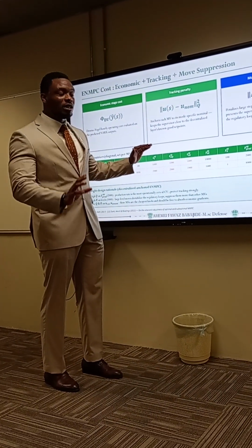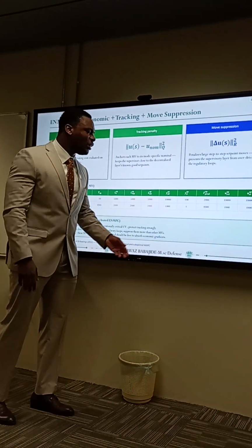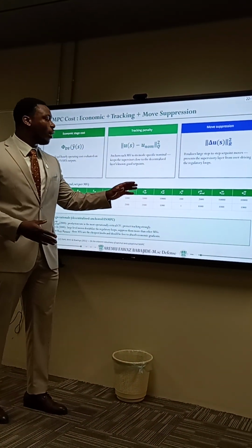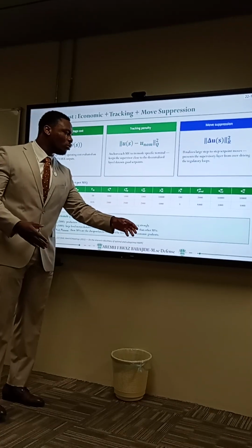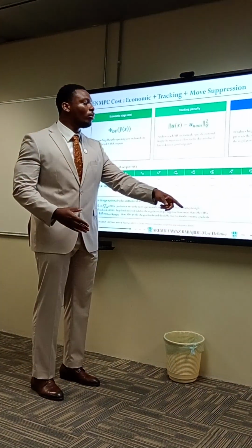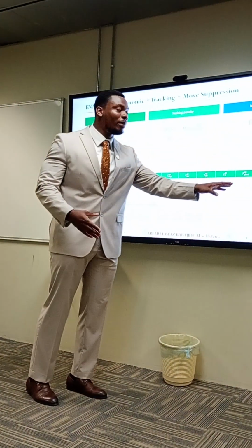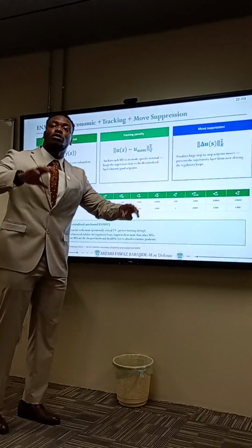And so we want to make sure that we have stabilized. We don't want our EMPC to change the levels that much. Same thing with the A to C ratio of reactants. Heavy penalty on those. Heavy penalty on the production set points. And of course, heavy penalty on the recycle valve, because according to the papers and the literature, we don't want it to open so much.